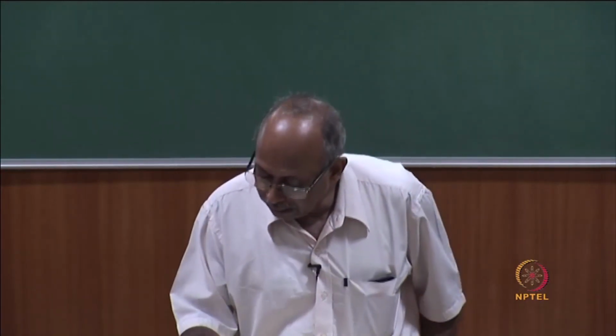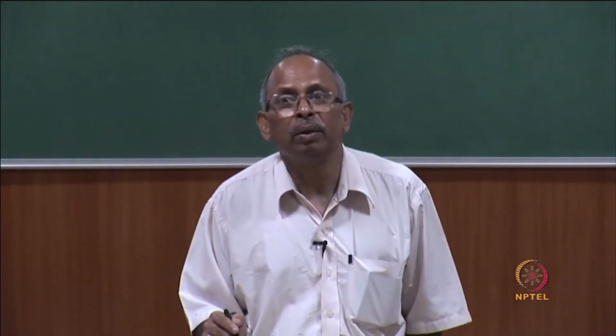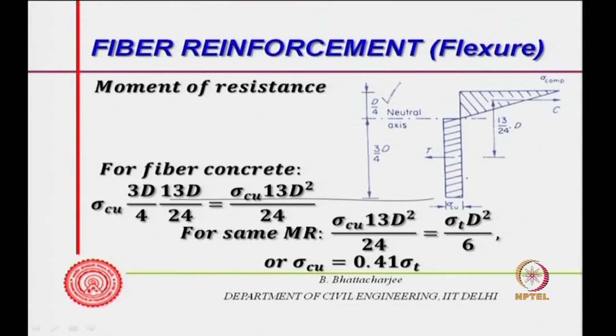The stress block in the tension zone will be something like this, assuming this is the smallest one, sigma Cu, the least value, as I showed you, the idealized one. Approximately one can take this as d by 4, because it was d by 2, now I take it to be d by 4 at failure; strain has increased so much at the bottom.